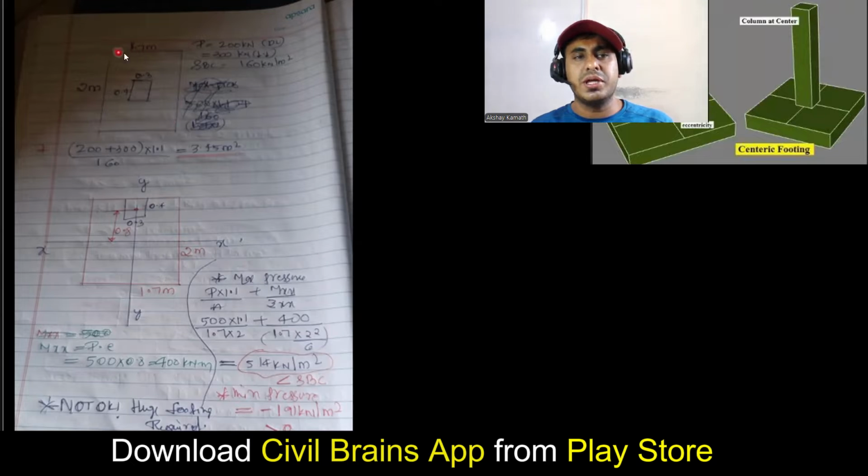Imagine that you have a footing, the size of the footing, the length is 2 meter, the breadth is 1.7 meter, it is mentioned here. We have a column, the size of the column is 300 mm by 400 mm. So it's a concentric footing. Your footing CG and column CG is matching. So let us say the live load coming is 300 kilonewton and the dead load is 200 kilonewton. SBC of the soil is 160.